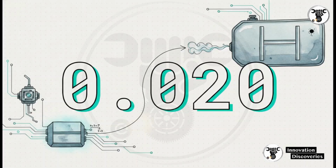What's really interesting here is this tiny number, 0.02 inches, or just half a millimeter. That represents the microscopic EVAP leak size that this sensor is responsible for detecting. The engine computer seals the system, watches the pressure data from this sensor, and if it sees a pressure drop indicating a hole the size of a tiny pinprick, it sets off the alarm. That is an incredibly tight tolerance.